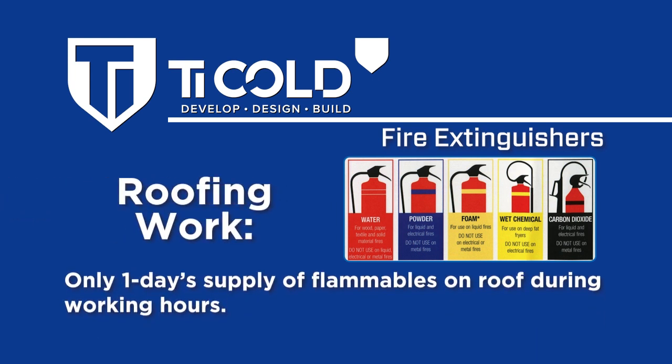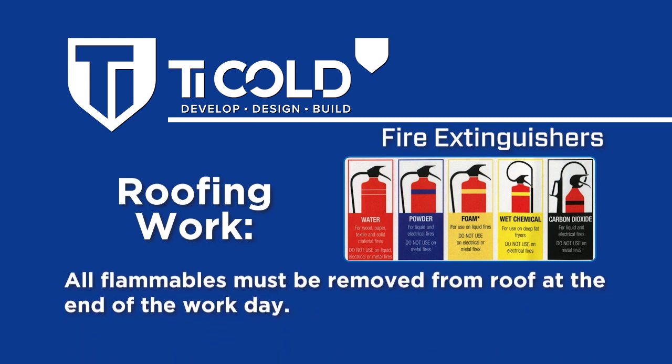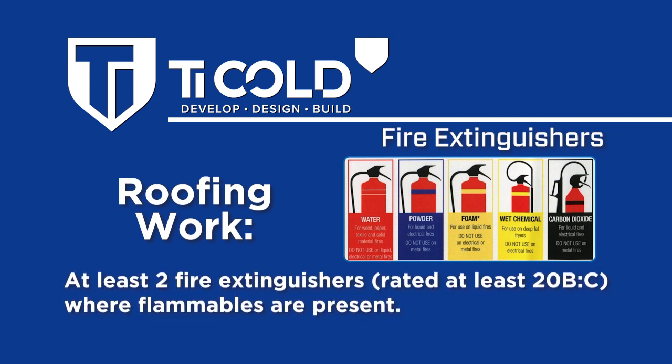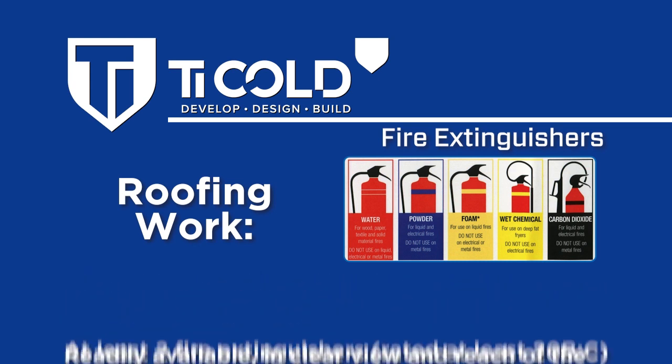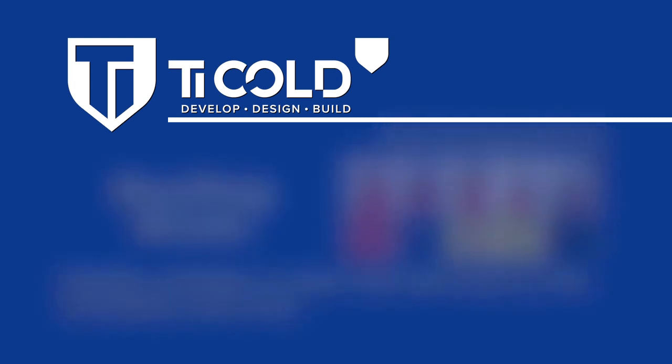Roofing work. Only 1 day's supply of flammables on the roof during working hours. All flammables must be removed from the roof at the end of the workday. At least 2 fire extinguishers rated at least 20 BC where flammables are present. Readily available in clear view and reach of the immediate work area.